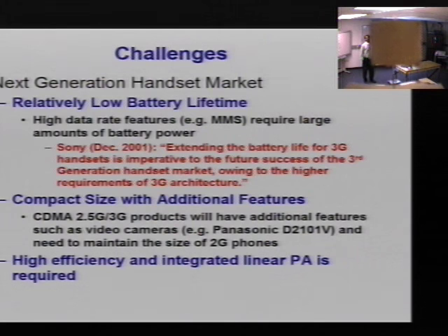So in CDMA 2000, the data frame of the small slot is actually 1.25 milliseconds. And in wideband CDMA, it's 0.625, so it's even shorter. And OFDM operates on about the same frame rate. So it means you have to meet much smoother requirements. That's true. Very true. But it's not all.